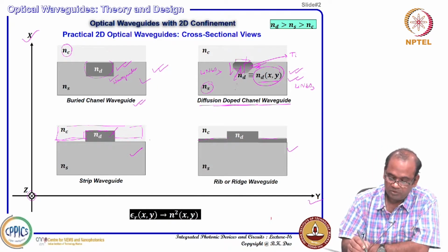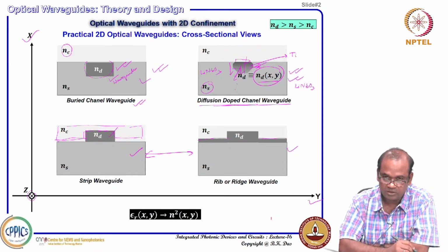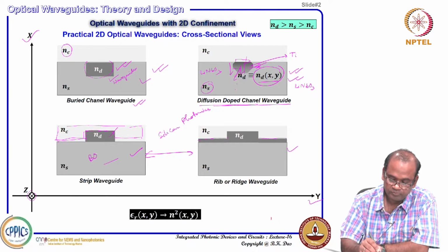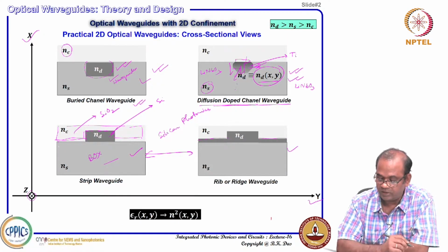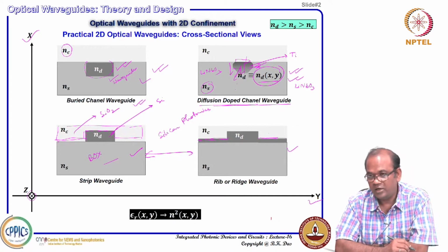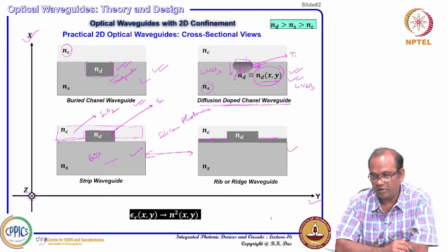These two types of waveguide cross section are normally used for silicon photonics applications, where this one will be just a box and this one will be your device layer, silicon, and the top can again be SiO2, air or silicon nitride, whatever, and you can leave some silicon material for certain kinds of electro-optic and electronic circuit integration.